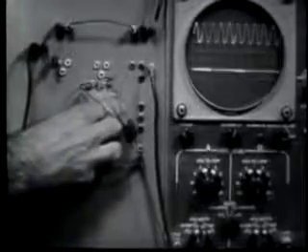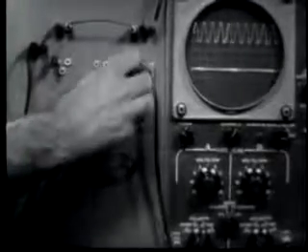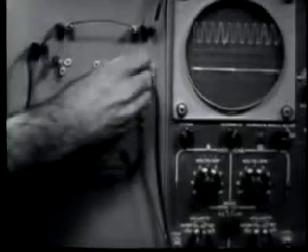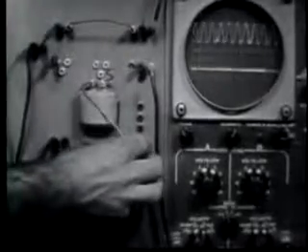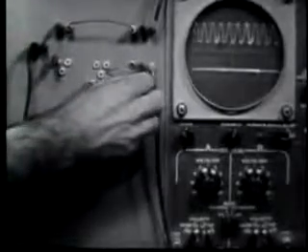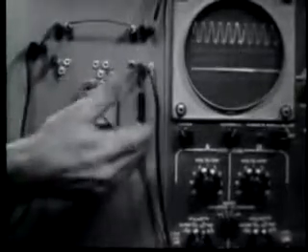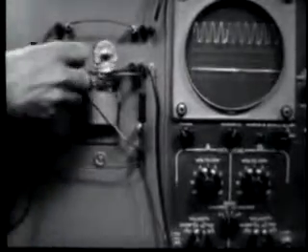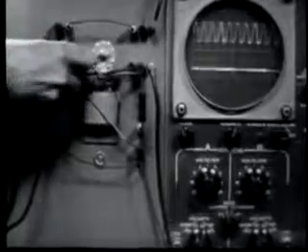First, I'll put in the inductor. Remember now, we're going to make a parallel tank circuit. So we'll put the inductor in here, just like that. Now, there's the inductor. In parallel with that, we'll hook the capacitor. Now, there's our parallel tank circuit. Now, we need a resistor to complete the circuit, and we'll use one of the resistors that we used in the first lesson, a variable resistor, set to the correct resistance to operate the circuit. Just get it plugged in there now.